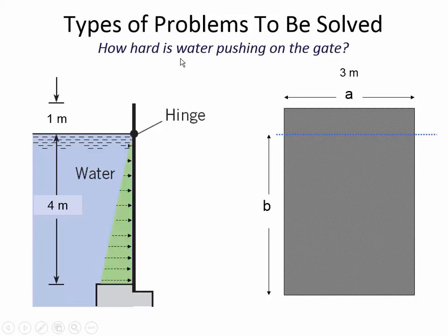What it'll depend on is the increase in pressure. You can see that there's a linear increase in pressure. There's a triangular pressure distribution here where there's 0 pressure at the top and the pressure at the bottom is the highest. Does anybody remember what the slope of this line is? It's the unit weight. Because if we go back to the hydrostatic equation, delta P is delta H times gamma, where gamma is the unit weight. This gamma, the unit weight of water, is the rate of pressure increase.